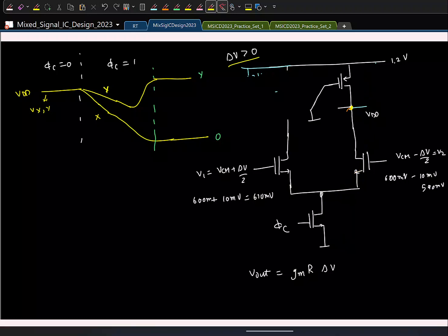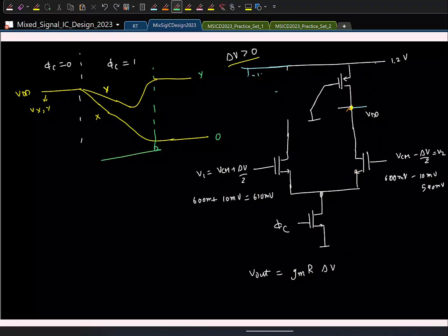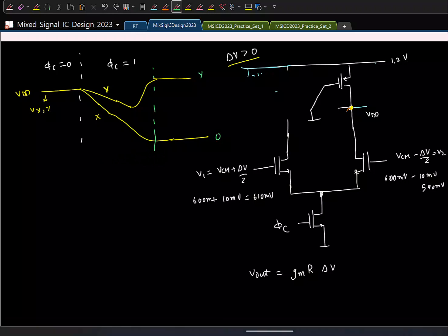Fine. So the point I'm making is, even after you finish making the comparison, which is at this point, at this point, you have finished making comparison. There is no need for you to burn power in principle. But even after you finish it, you are still burning power in this time. Okay. So here we have an unnecessary static power consumption. Even though the inputs are not changing, outputs are not changing, you are unnecessarily burning power.